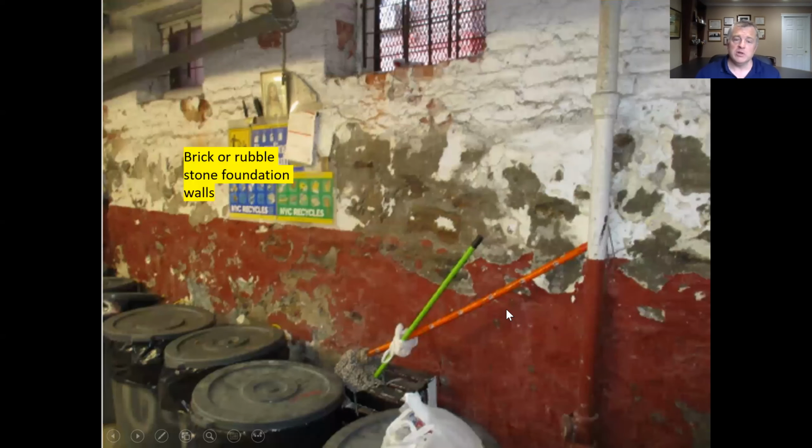First of all, new building: poured in place concrete foundation. The walls that support your first floor and above, that you see from the cellar, are poured concrete. Old world building: brick or rubble stone foundation. Rubble stone is literally just stone with some grout, some glue, and that's what transferred the load to the earth. Is it bad? No, it's actually terrific. Some of these 120-year-old buildings haven't moved an inch, and they're going to last another 120 years. They were structurally very, very well built. That's the foundation system. We'll get into some of the things above the foundation system.